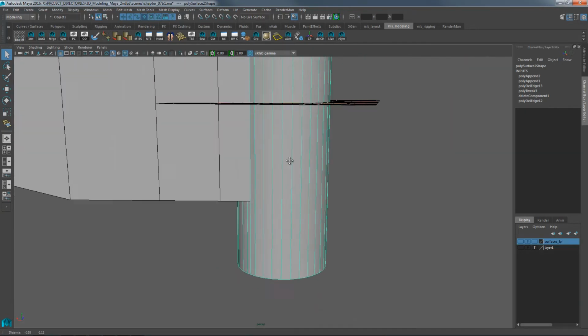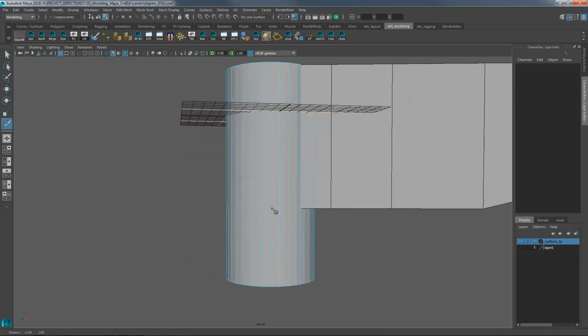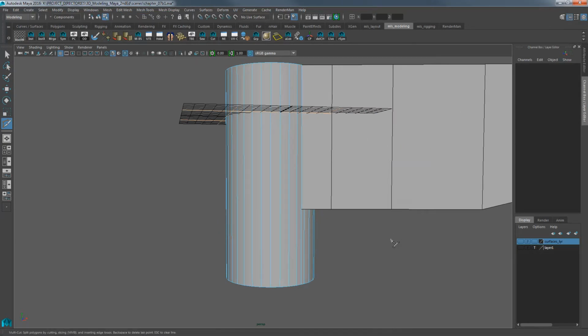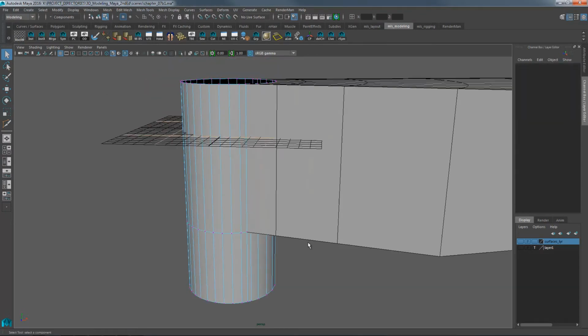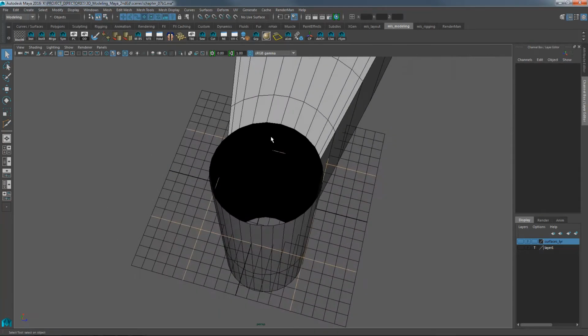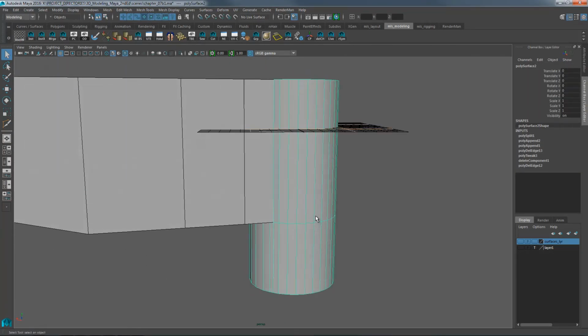And now we can add those edge loops that we need. So I'm going to get multi-cut one more time. Make sure that edge flow is not on. So I'm holding Shift and Control and right clicking. Make sure edge flow is not on. Control, click, and then tag all those vertices and set them to absolute value -10. One more time. Good. Now that all lines up on the inside, lines up along the bottom.